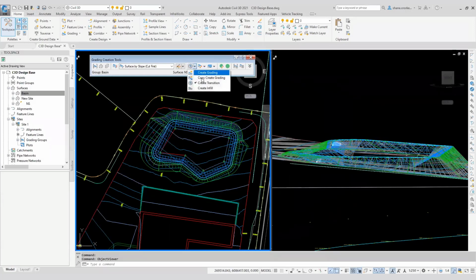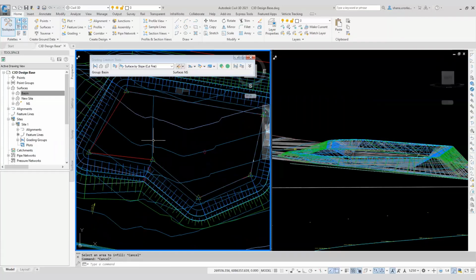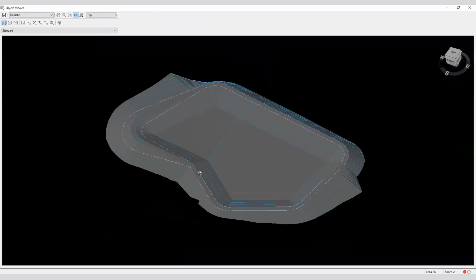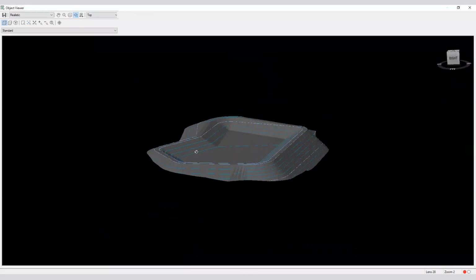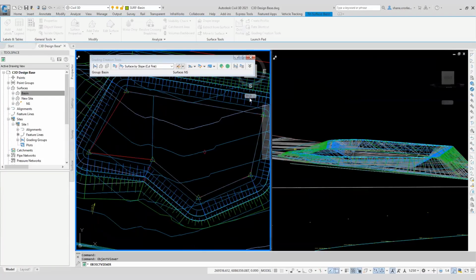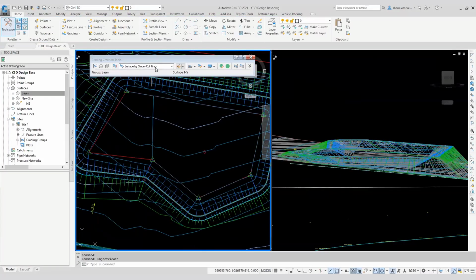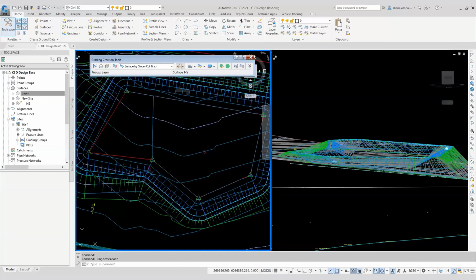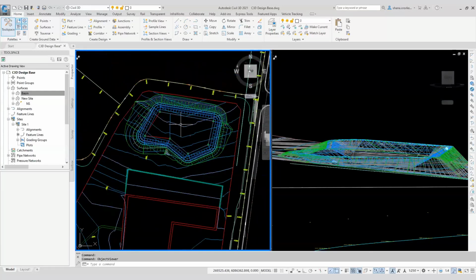To get rid of that, you add what's called an infill. Once you do it, you get a little diamond here. So there's not a lot to tell you what's going on, but there is now a surface happening internally. So now if you calculate earthworks, it's going to be all good. So the thing about grading is you've got these rules, they'll create solids, and the grading group will also drive you a surface.